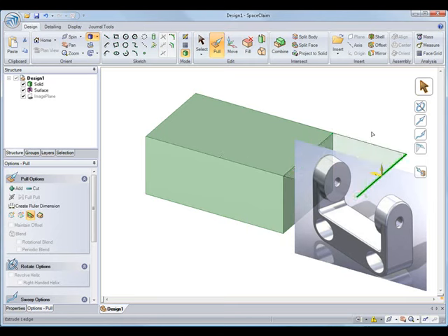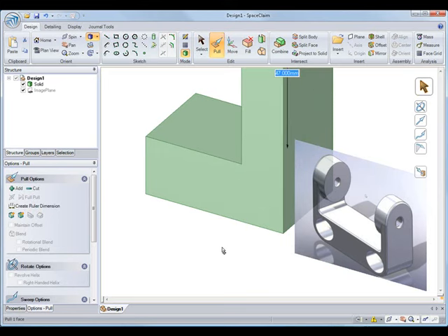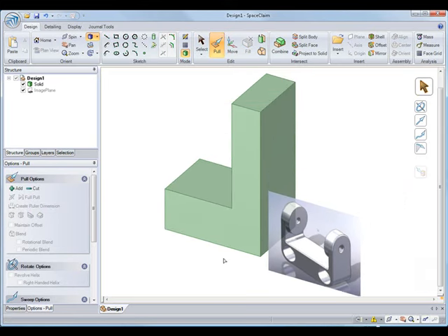So normally that creates a surface if I extend it one way or the next, but if I hold down Control, it actually copies that line, just like if I move and hold Control, it'll copy a face or copy a hole to a different location. So now that I have our region pulled up, I'll just select the top two edges and turn this back into a round and put a full round on top.